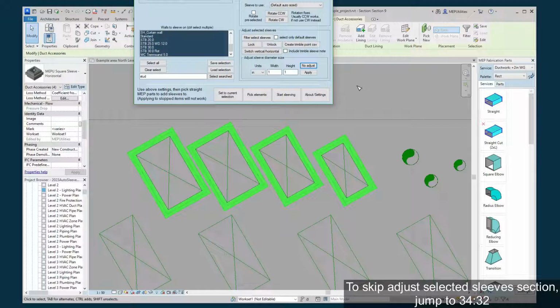Because as you would know, this is automatically sized. Those sleeves aren't actual created items. If you make custom sleeves, this is great, because you can just build custom sleeves to match these dimensions. But if you don't have that, and you're using a preset one, you're going to want to use a pre-built sleeve part that you make with the dimensions that are correct.